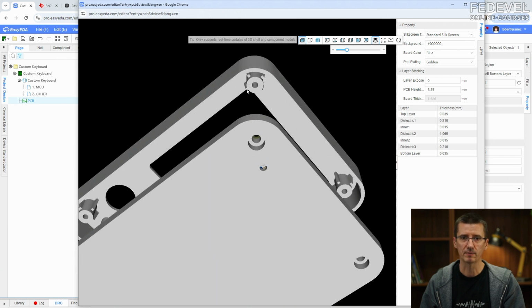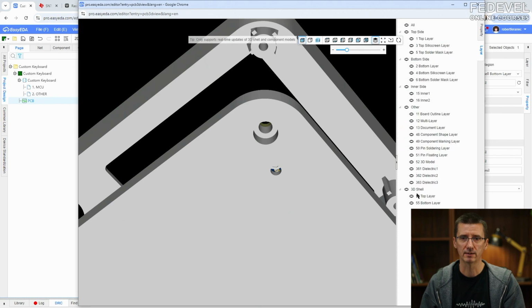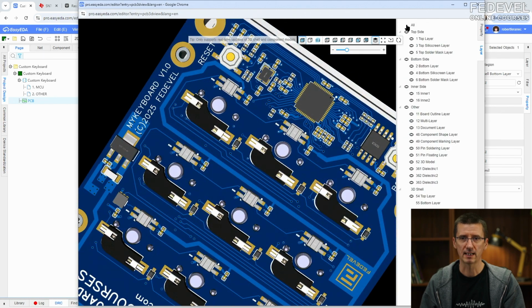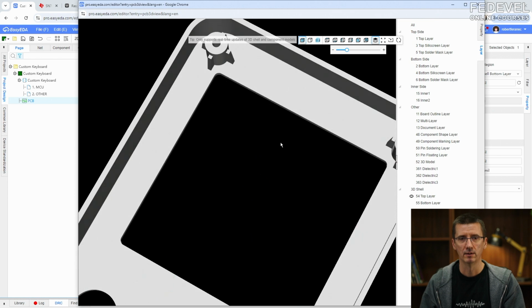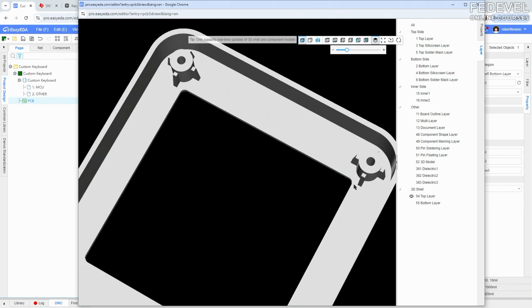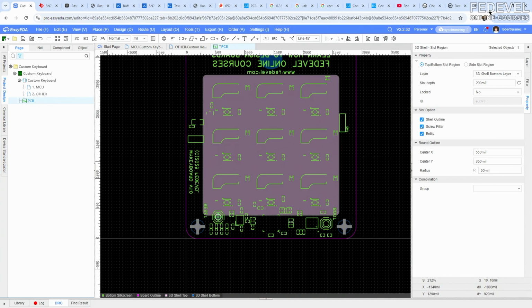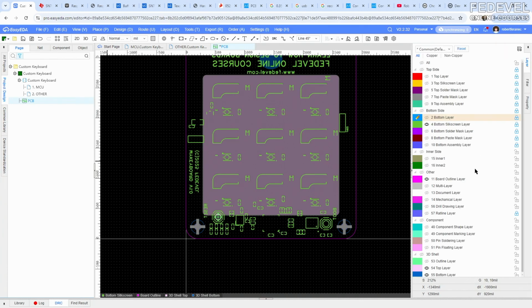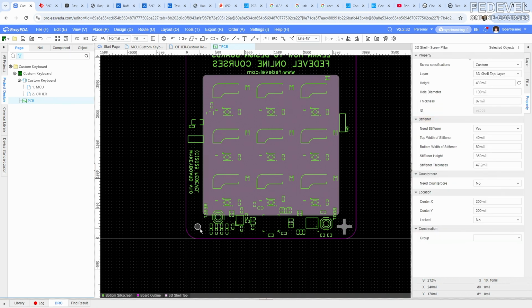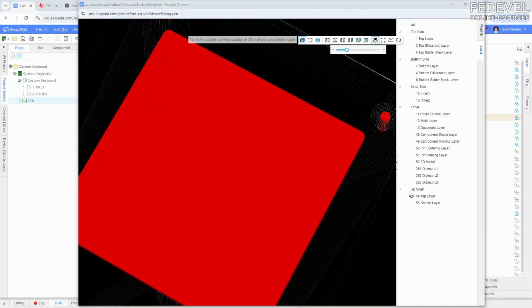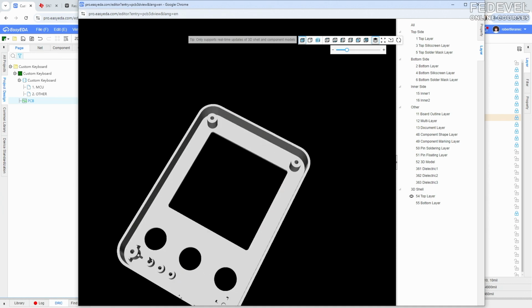And we need to remove these ribs around the pillars, because as I said, they are in collision with the metal plate for the switches. This is the problem, these two. But we have to remove all 4 of them, and it's very simple. We just would like to work with top and disable this. Disable it also here, and double check. Okay, see?